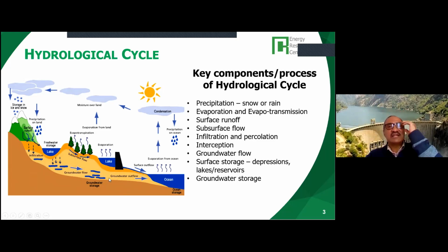So it is very important that the catchment area is not, I mean, if it is all covered with concrete, there is very little groundwater recharge. So the water available in the dry season in such places will be low. But if you have a catchment which is forested and has open surfaces, then you can have groundwater recharge, which will come back as the base flow in the dry season.